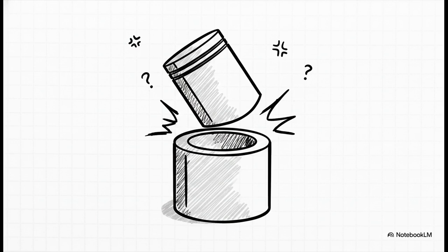There's this fascinating case study from a Cal State Sacramento thesis involving first-year engineering students. They were tasked with building a working steam engine. The whole project was practically ruined because the students manufactured mating components that were perfectly flat, but they weren't oriented parallel to their required datums. Because of that single orientation failure, the engines simply could not be put together. A tough but really valuable lesson.